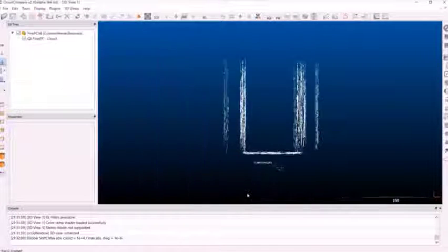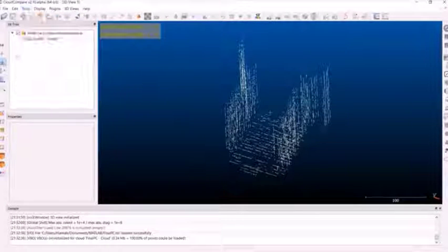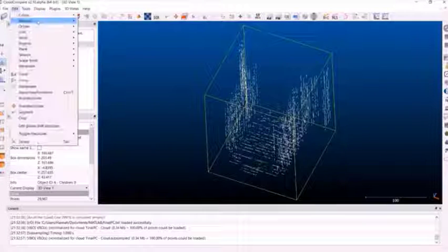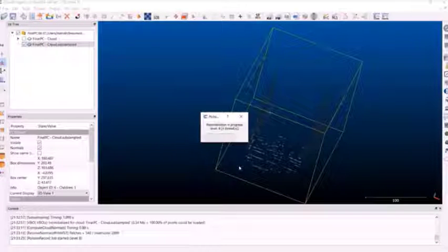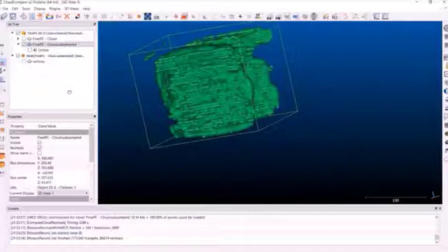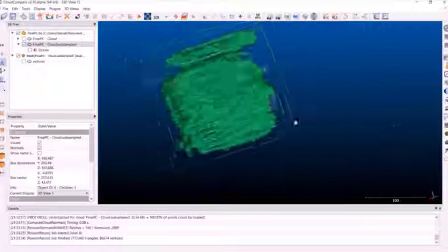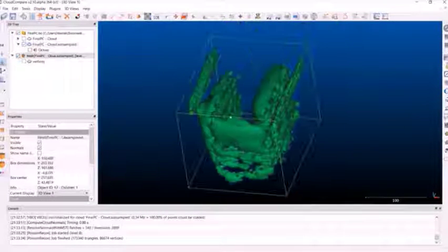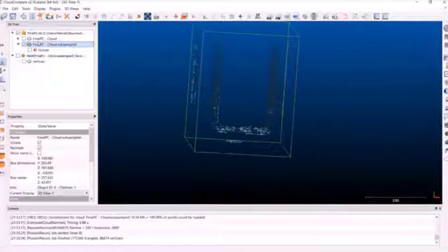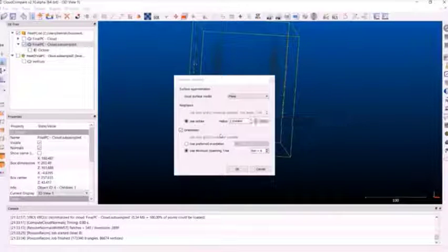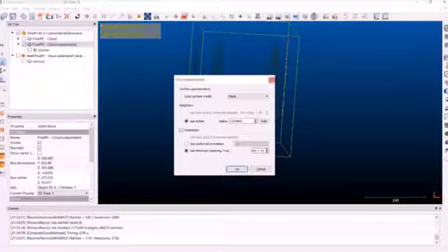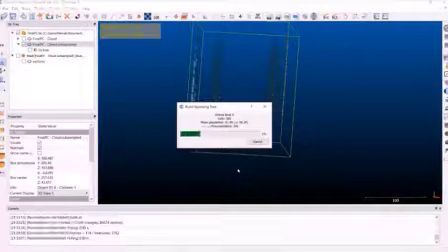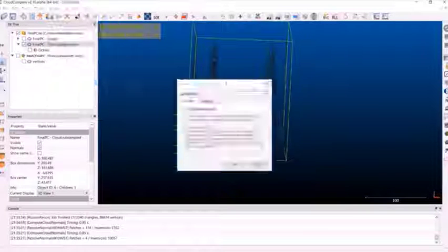To begin meshing my final filtered point cloud, I first imported the point cloud into Cloud Compare. I then computed the normals for the mesh and used the preset number of neighbors, which was 6. I applied a Poisson surface reconstruction to generate a mesh, but the resulting mesh had a lot of empty space, which was anticipated because the points making up the 3 faces of the ATM are far apart. However, I recomputed the normals, this time with a much higher neighbor number, and remeshed in hopes of filling in some of this empty space and connecting the sides of the ATM with one another.